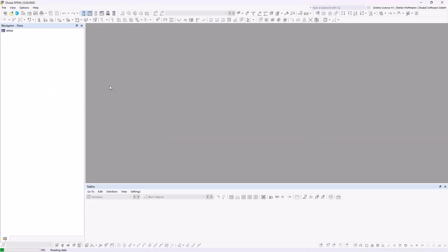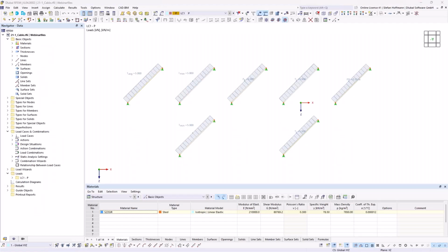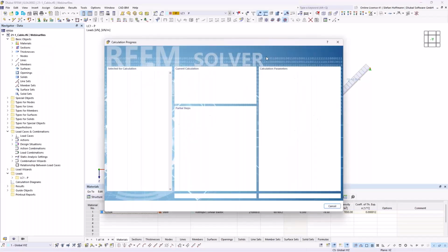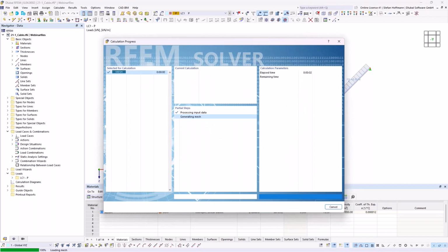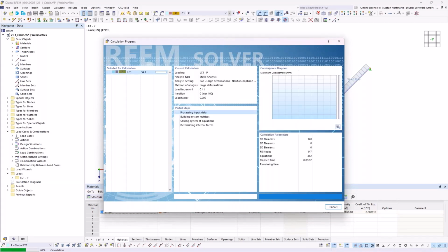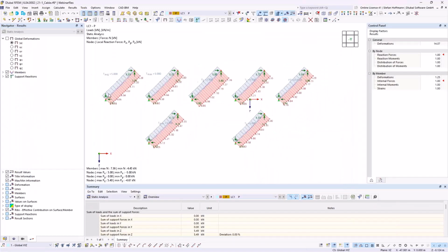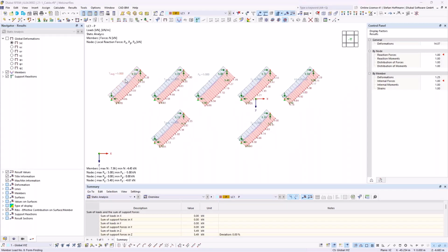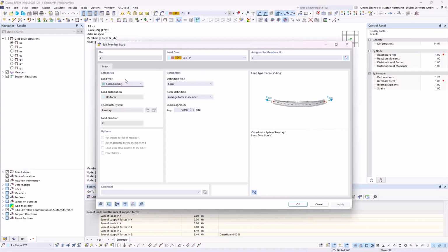This is called cable, where I would like to introduce you once to our cable loads. So I will just run the file once. It's the same cable, a 10 times 10 meter with a 45-degree angle cable, so 10 meters times 10 meters. So it's 14.1 meters. And then if we go into our load definition, as told for the surface loads, it's not now a setting of a surface or a setting of the member. It is a load you can assign as a member load.